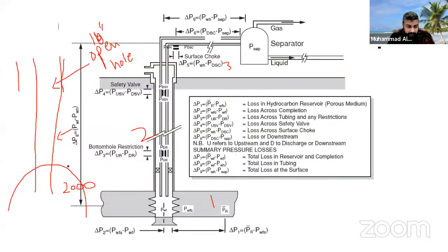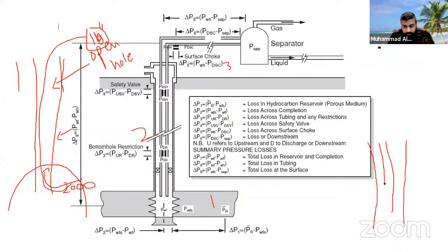Now, the oil will try to go through this 10 inch open diameter, and the pressure at the reservoir may not be enough for your oil to go towards the surface. It's not necessarily enough from the bottom to the surface because the opening is just too big. It's 10 inch. On the other side, you don't leave the 10 inch. You have an open hole here and you install some tubing. The tubing reduces the diameter to 2.5 inch. Now it is a very narrow pipe. So you still have the open hole, but you install the tubing so your oil can flow inside this restricted diameter. Now the oil will flow faster because you have restricted the diameter of the hole, so the oil can flow easily from the bottom to the top.